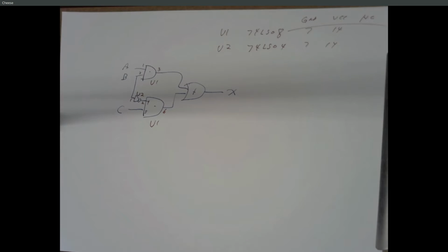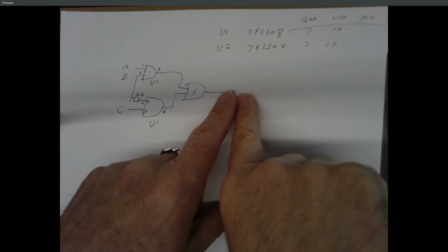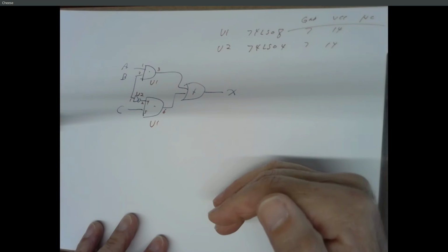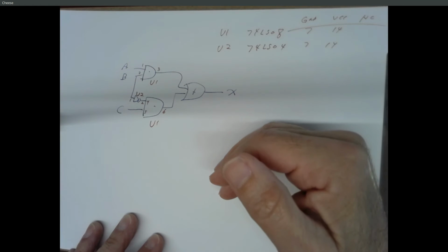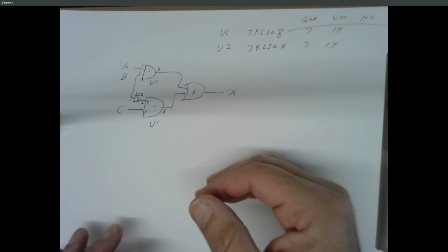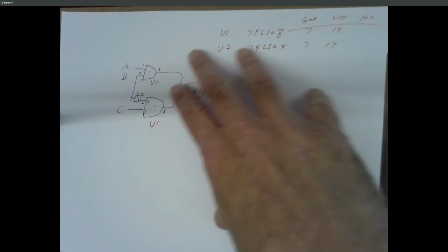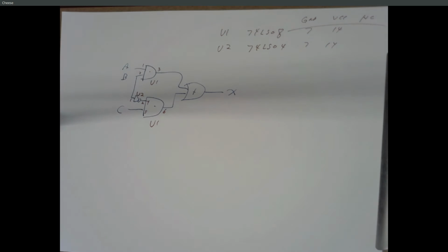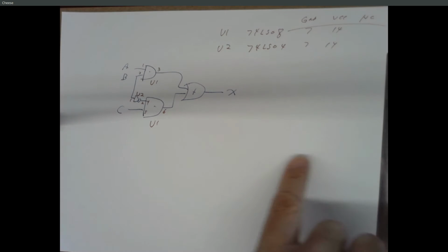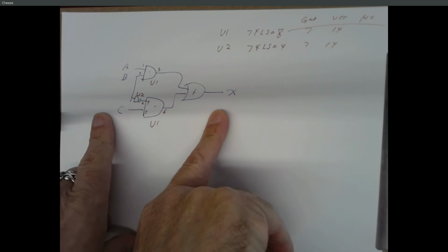To go from a truth table to a circuit, you've got to have equations, right? So in some cases, I saw the equations written over here, but write out those equations, and hopefully you're simplifying, right? A few people didn't simplify, and you get a very complex circuit. That's not wrong, but if you simplify, it makes things a little easier, or a lot easier in this case. So you'd show your K-maps or whatever algebra you're doing to get your simplified equations. And once you have your final equations, then you make the circuit diagram that corresponds to that.